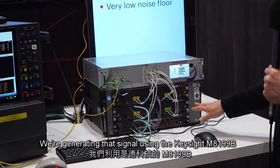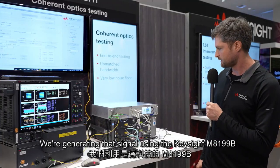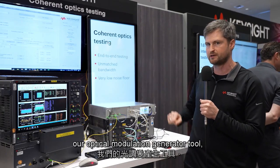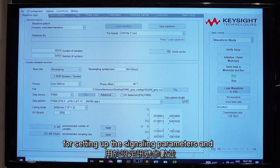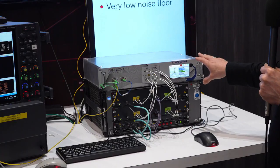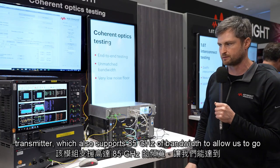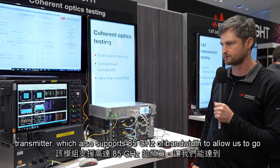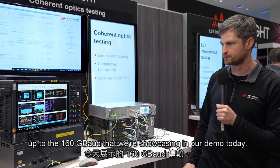We're generating that signal using the Keysight M8199B arbitrary waveform generator and use the software, our optical modulation generator tool, which mimics a coherent optical DSP for setting up the signaling parameters and de-embedding the waveforms. We modulate the signal onto an optical carrier using the optical multi-format transmitter, which also supports 85 gigahertz of bandwidth to allow us to go up to the 160 gigabaud that we're showcasing in our demo today.